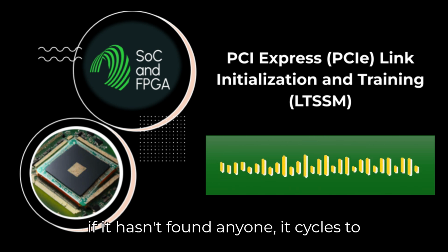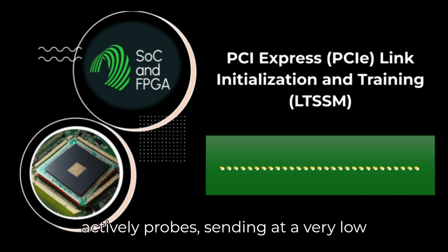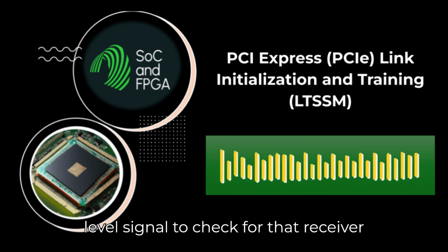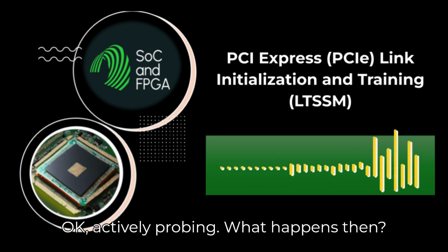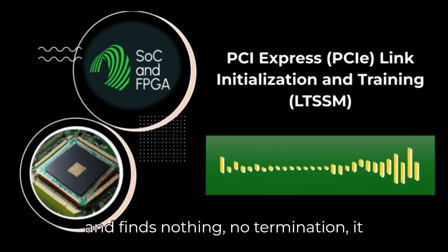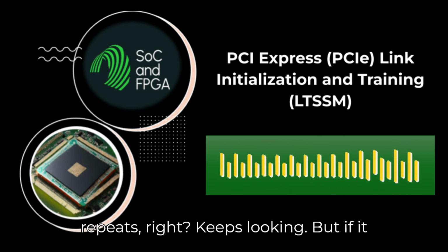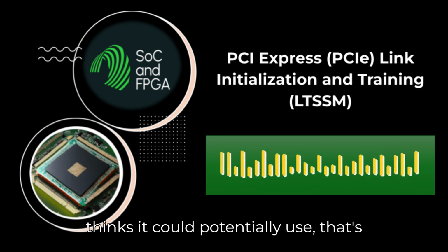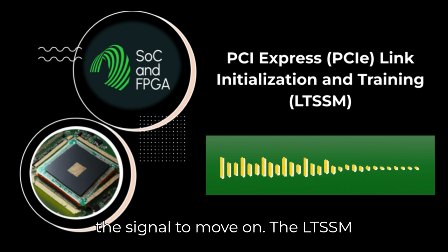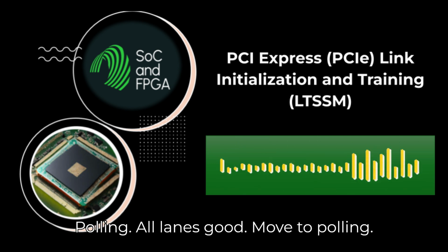Then, if it hasn't found anyone, it cycles to detect.active. Here, the PHY actively probes, sending out a very low-level signal to check for that receiver termination. Okay, actively probing. What are the outcomes? Well, if it probes and finds nothing, no termination, it just goes back to detect.quiet. The cycle repeats. But if it detects termination on all the lanes it thinks it could potentially use, that's the signal to move on. The LTSSM progresses to the next major state, polling.